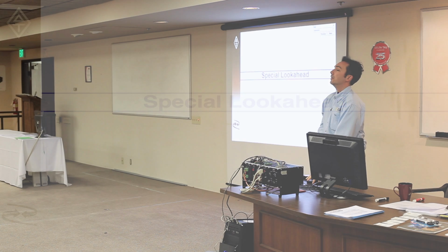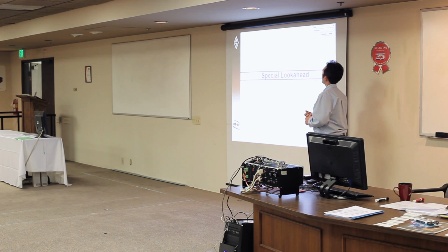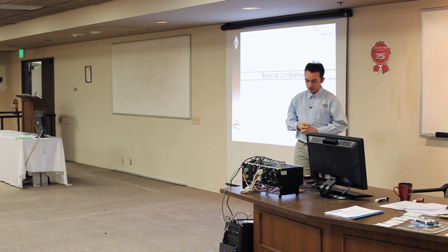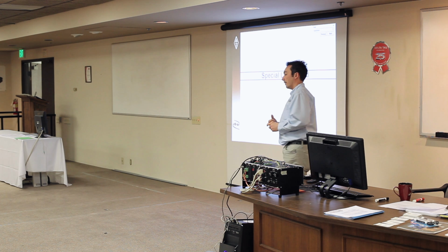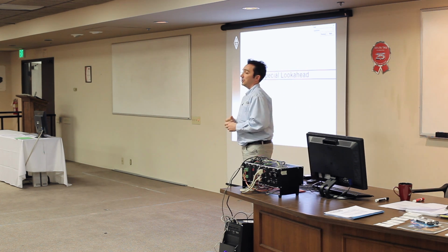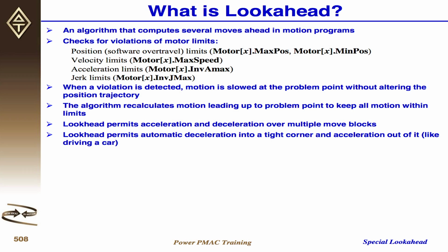Depends on the size of the definition of this lookahead buffer, it can look ahead more segments, and that gives you the advantage of checking the velocity and acceleration violations of the path of the trajectory. This algorithm computes several moves ahead in motion programs. It checks for violations